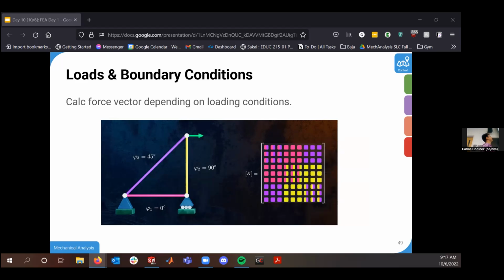There's a critical piece you also need to keep in mind: I no longer have connections that just go in a linear fashion, like node 1 connects to node 3 and 2. I have intersections both here and here. For each one of those connections, I now need to apply a rotation depending on the geometry and how it connects to the global coordinate frame.